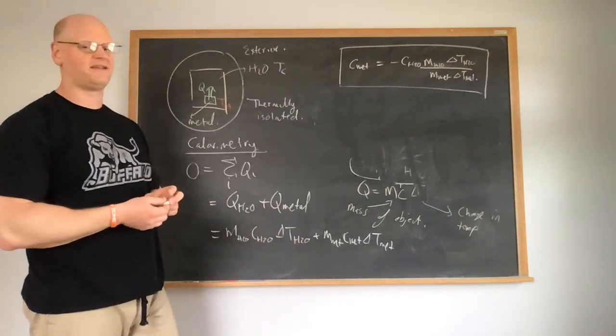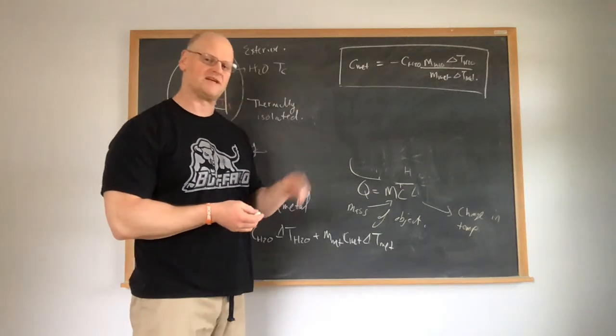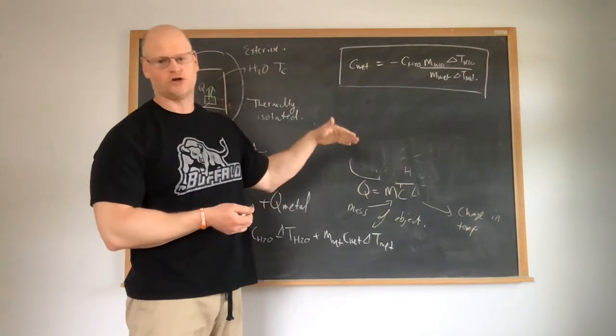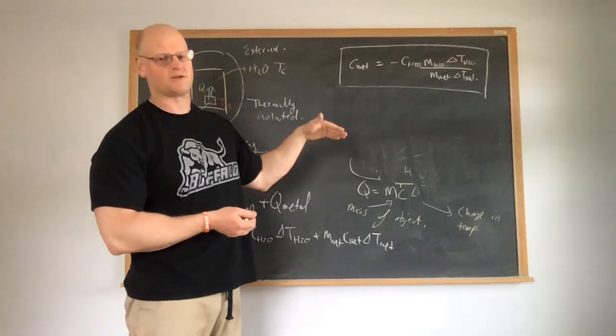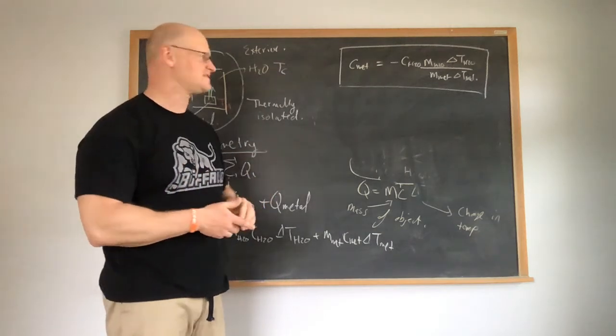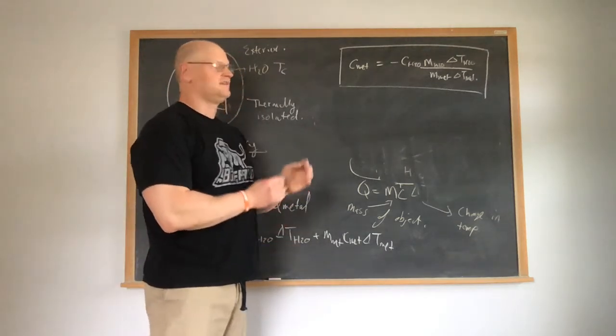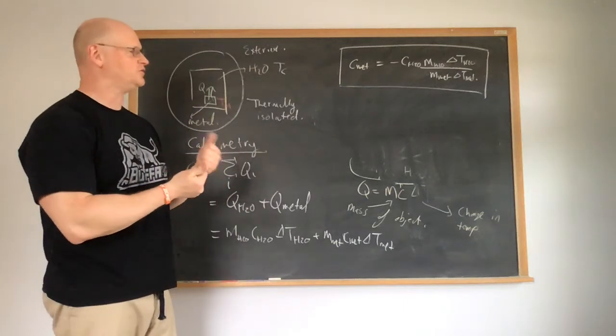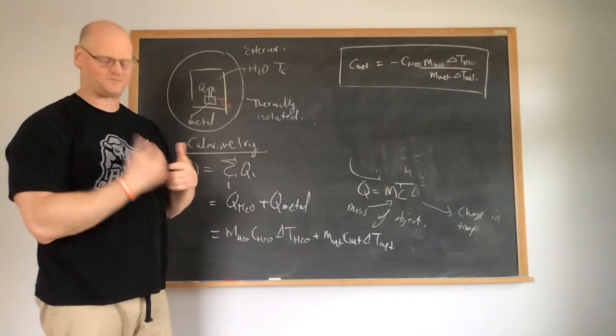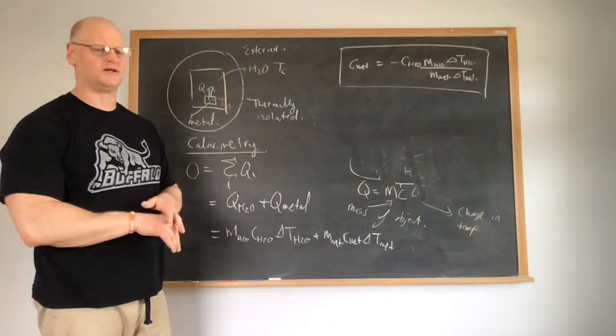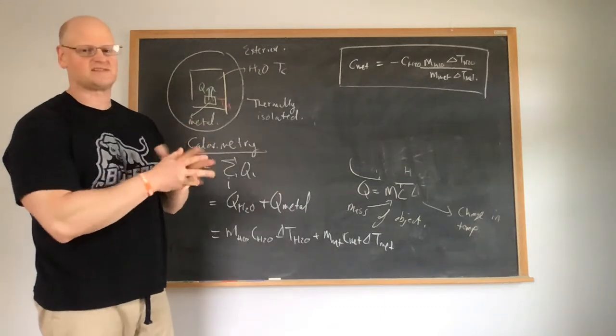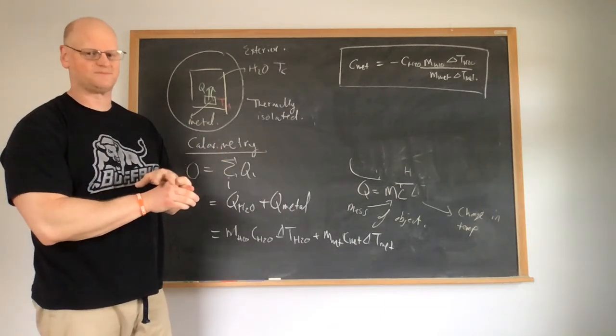You also want to find the discrepancy because once you know what the metal is, you look up what the specific heat is of that particular metal, either in a textbook or online or any place that you want to. And then from there, that'll be the accepted value. You'll have your experimental value. So then you can calculate your discrepancies, so both the absolute and relative discrepancies.